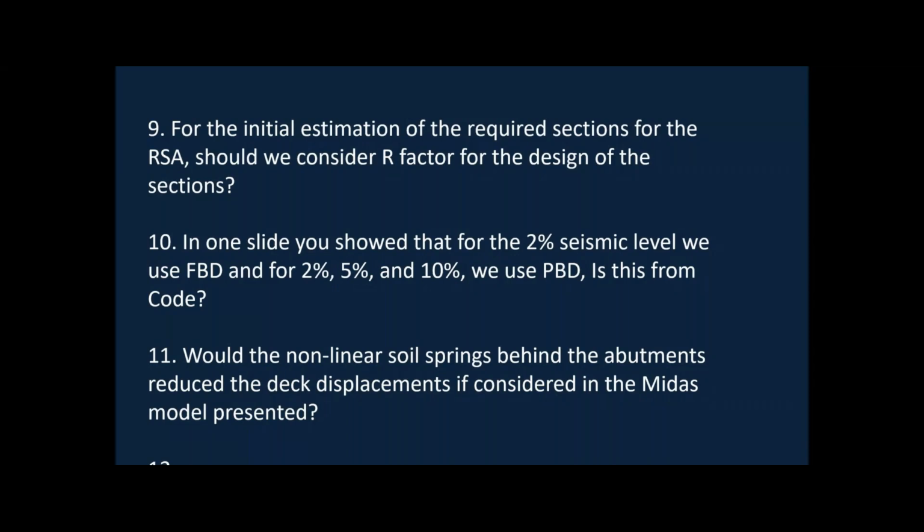But if you want to consider it, the Caltrans SDC criteria provides the nonlinear spring stiffness to be used for the abutments, and that entirely depends upon the depth of the abutment and the angle of internal friction. So we can use that to compute the nonlinear soil spring stiffness given in the Caltrans SDC.